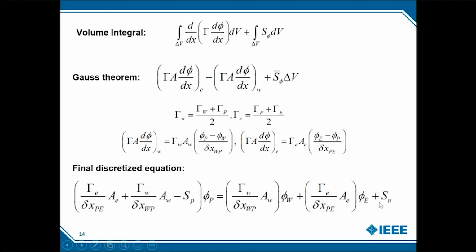Again, phi is just a representation of a variable that you're trying to solve. This can very well be just a temperature. Phi can be temperature if you're solving for a temperature plot. It can be any other quantity you're solving for. I've just given a general notation over here. And that is what we do. So we get a set of algebraic equations, and we use multiple numerical methods and matrices to solve this. This is what happens in the background if you have set up any Fluent simulation and you have hit run. What happens in the background is something you never see.